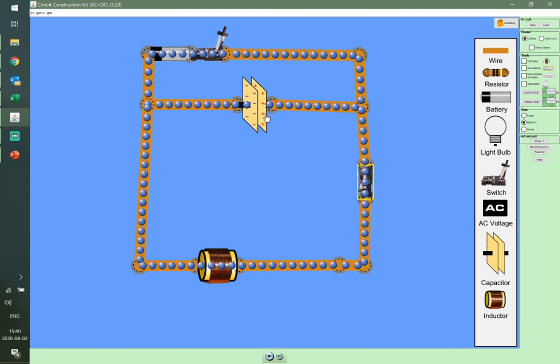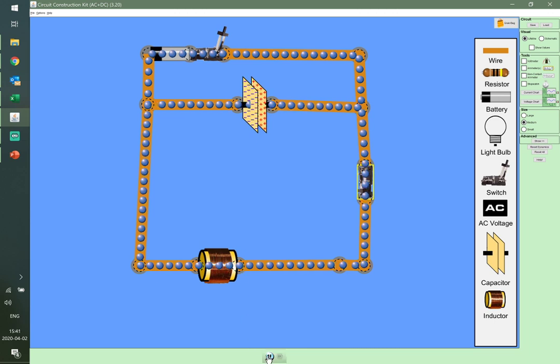But when the capacitor becomes totally discharged and stops pushing things clockwise, what's happening is that the inductor now has a current through it. So it wants to maintain that current in the same direction. So it continues pushing the current in the clockwise direction, putting some negative charges onto the other plate until it gets built up enough that the current stops and we go back the other way. And this time we go back, it's going to overshoot again because of the inductor trying to keep it going. And then just go back and forth like that.